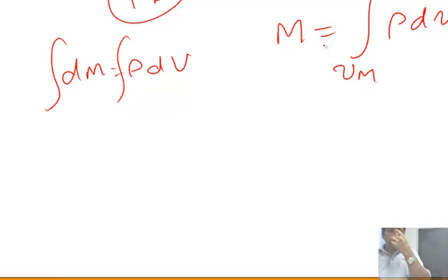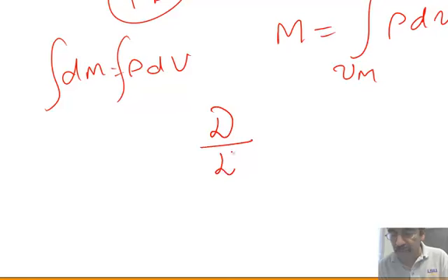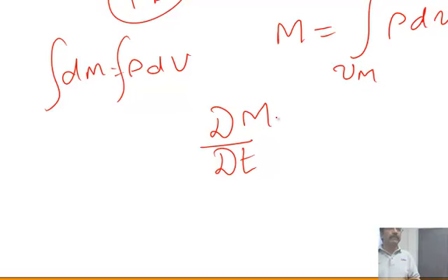It can change its shape, but it has the same material forever. That is how we define a material volume. So what is the rate of change of the mass of that material volume in the Lagrangian sense? Zero. That's how simple it is to write the material balance equation in a Lagrangian frame.